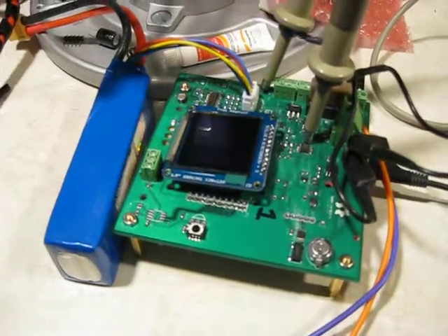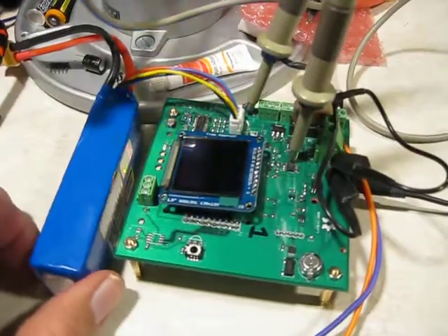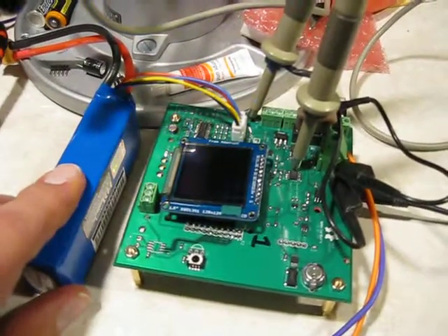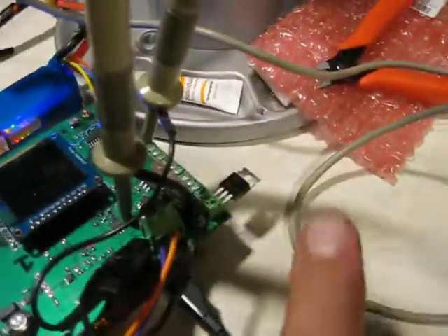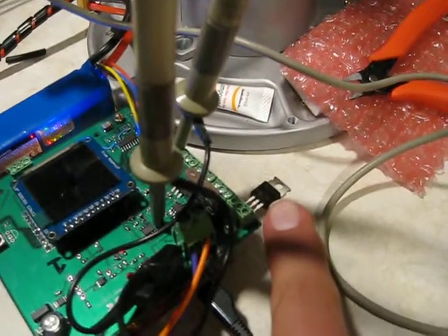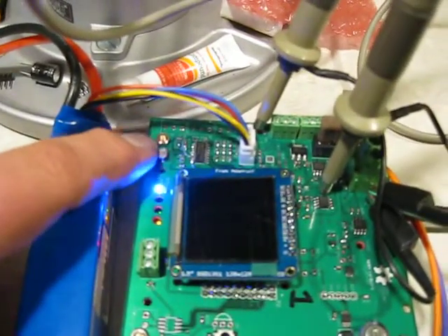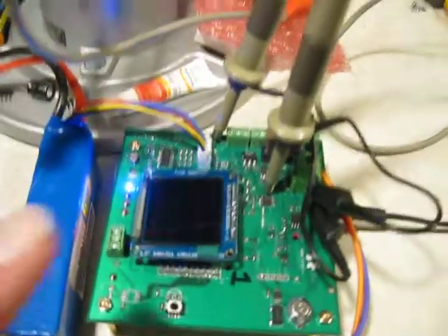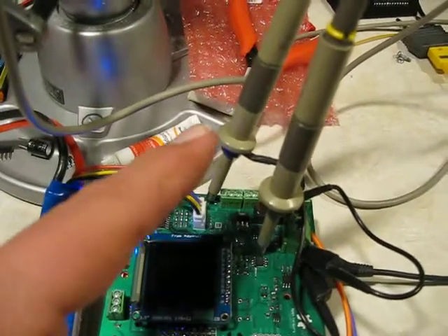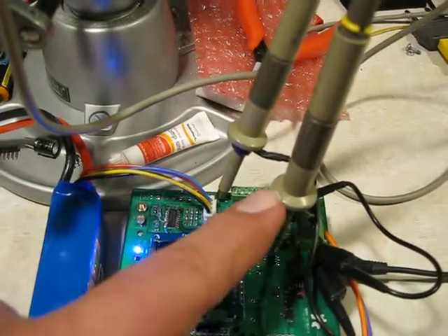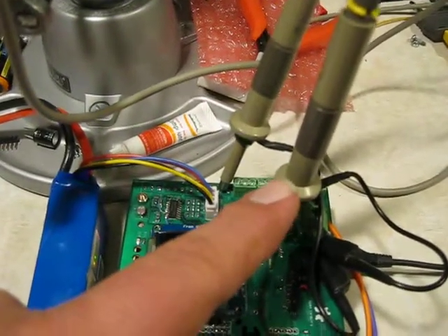Here's the SolOhm board I'm doing some software development for today. I have it powered on a LiPo battery, and I have a single pass transistor over here. This is the activity light, this blue one here, and the day sensor is over here. I have a couple of scope probes plugged in. This one is measuring the panel voltage, and this one's measuring the panel current.